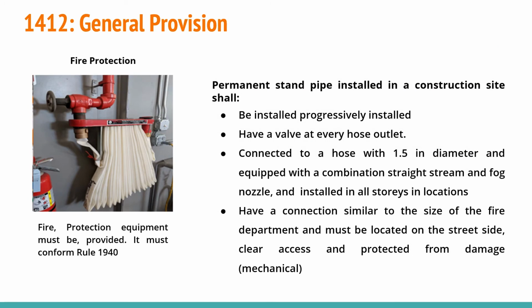So, fire protection. Fire protection is to have means to combat accidents in relation to fire. Permanent standpipes must be installed and be in strategic locations. It must be connected to a hose 1.5 inches in diameter and equipped with various nozzles: stream, straight, and fog. Ensure that the connection of the hoses is similar to the fire department standards and that it is protected and easily accessible.